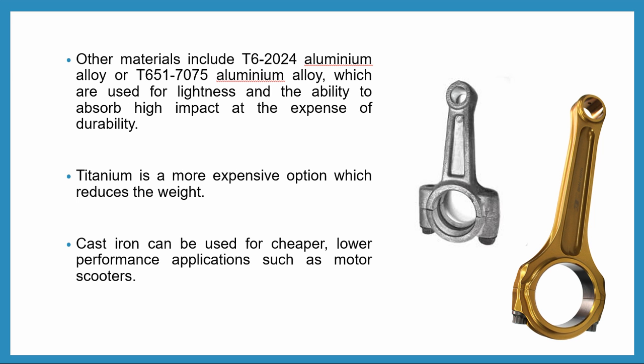Besides this steel, connecting rods use die forged methods for production. It basically uses die forging from special types of steel such as nickel chrome steel and chrome molybdenum steel.